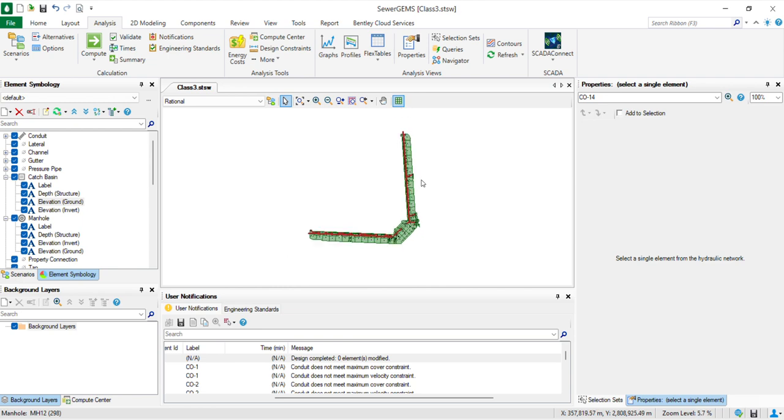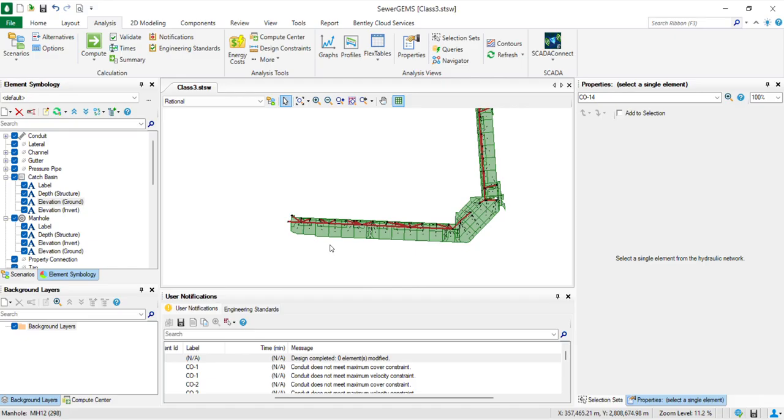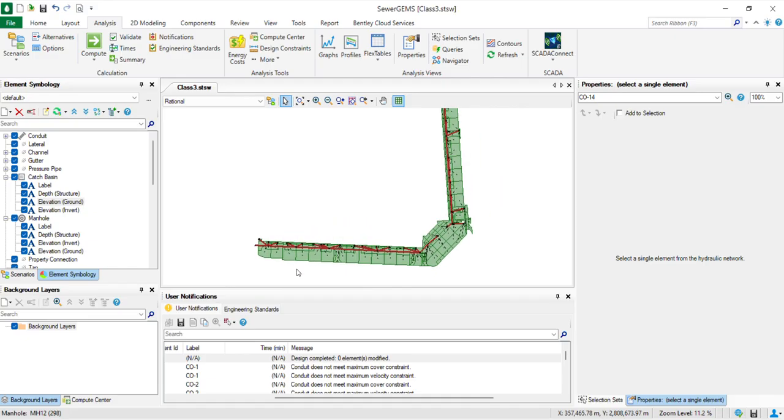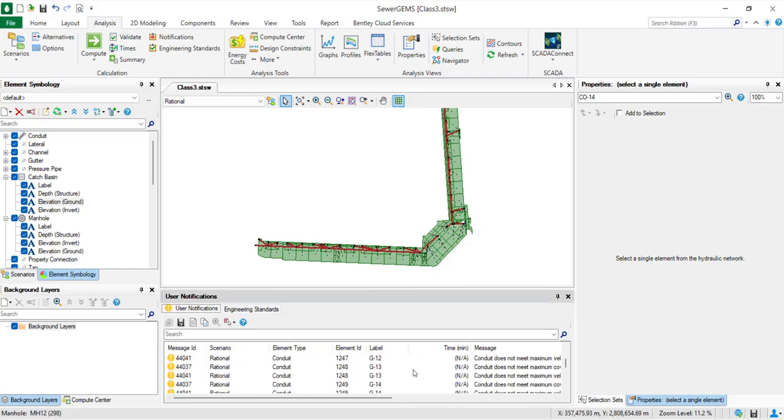Okay, I myself will tell. First we read the grading file and created the catchments. Then we placed the gullies at every 25 to 40 meter interval. Then we created manholes for the gully connections. Then we connected the gullies and manholes using GIS. Then catchment connection was also done in GIS. Then we set up everything like design constraints and catalog for gullies, manholes and catchments. Finally we have run the model without any error. This warning is nothing, no issue for this warning.